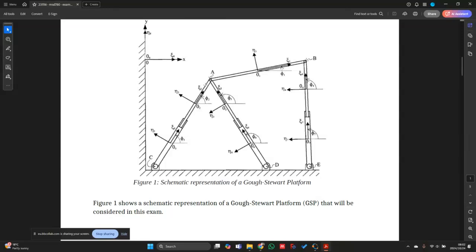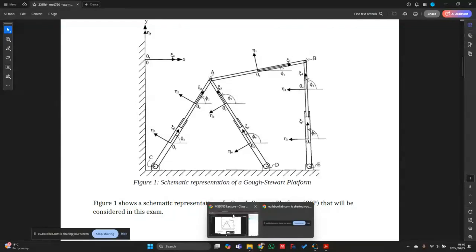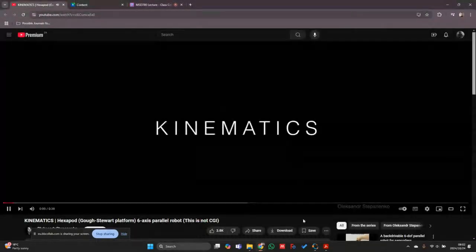Essentially what it has is 3 actuators over here, and this is now the planar version. Each actuator allows the load that is placed on the platform to be distributed along each actuator. So you get better load distribution and accuracy capabilities than when you compare it to something like a serial manipulator. Now, to just give you an idea of how the 6 degree of freedom goes.